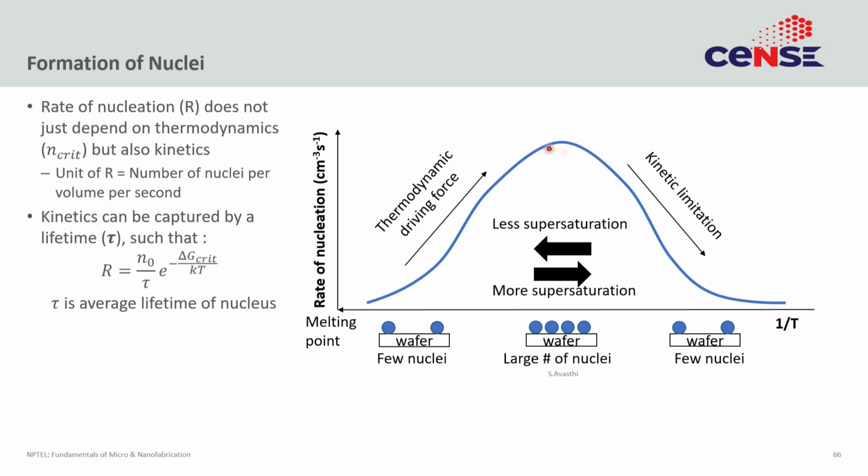At some point, however, it peaks and then it falls again, and this is because of the kinetic limitation. You see, nucleation must form by agglomerating subcritical nuclei, right? And then the nuclei sort of needs to grow, but that process requires movement of material, which again happens through diffusion. So there is a kinetic limit of how fast this can happen, and if you reduce the temperature too much, even though the driving force for forming the nuclei is very large, the kinetics or the speed at which the nuclei can form are so small that you don't really create a nuclei. So that's what leads to this U-shaped curve. This sort of an insight is important to tell you that nucleation rate peaks somewhere in the middle. It's not highest at the melting point, neither is it a monotonic decreasing function. It's a U-shaped curve function.